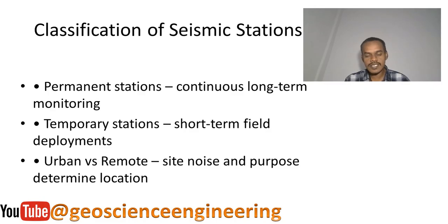And then data storage. When it comes to data storage, these seismic stations come with internal storage, like a USB stick in which the data is stored, and it will be overwritten every 5 days or at other frequencies. Some stations are directly connected to the server, so the data is sent directly from the instrument to the server and the records are stored for a longer time. And then the software controls, in which you go for calibration and data formatting, and if you want to check diagnostics, you can use the software, or sometimes a web interface, to control your seismic equipment.